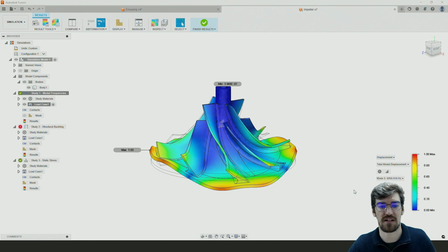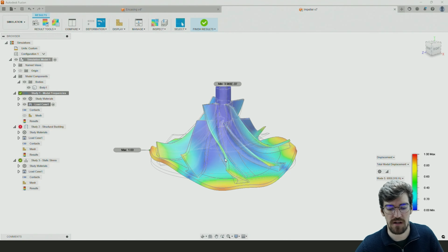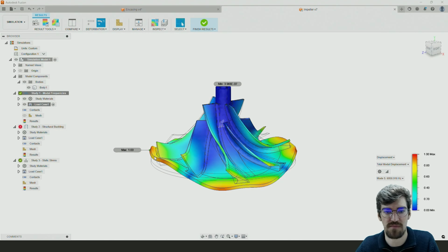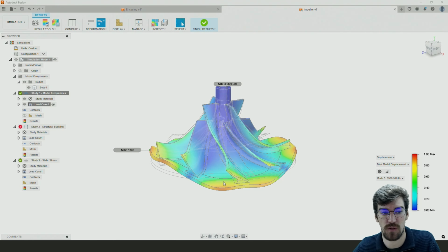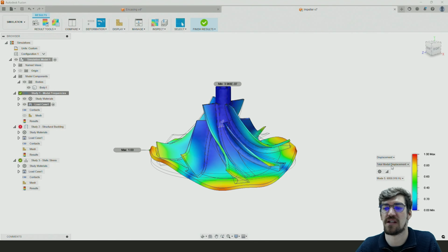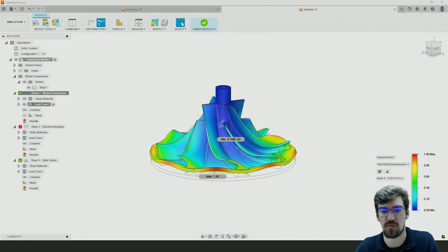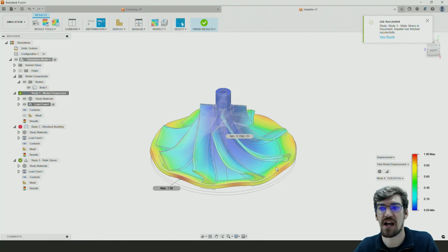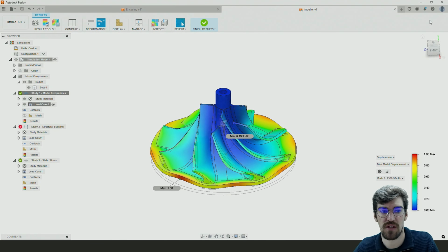The displacement is a little bit disorientating, and don't worry too much about the actual displacement in here. That's why it's been set to 1 as a maximum. It doesn't mean too much. It's not exactly how much it's going to deform by. The important thing when we're looking at these studies is the actual frequency itself that we need to worry about. So we've now got a result of all of the frequencies that we might want to begin to avoid as part of the process itself.